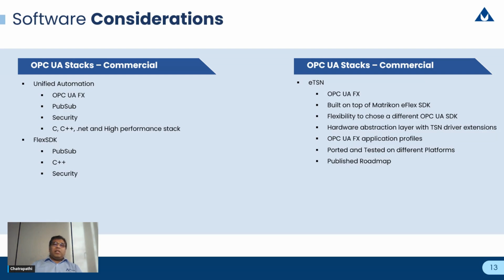And additionally, it has a flexibility for you to choose your own OPC SDK and integrate it as well. So it comes with the Flex SDK already integrated, but you can also choose to integrate a different OPC UA SDK and still leverage all these additional interfaces and drivers and packages that are implemented for making it easy for any OPC UA FX product development.